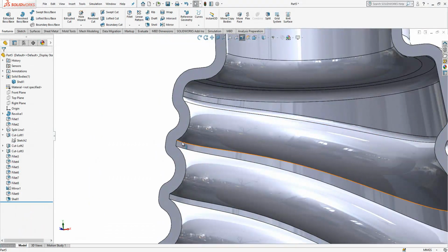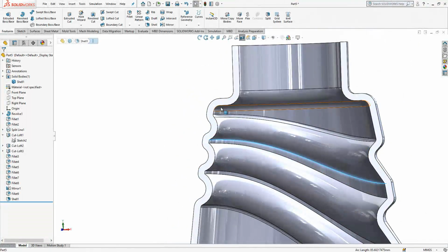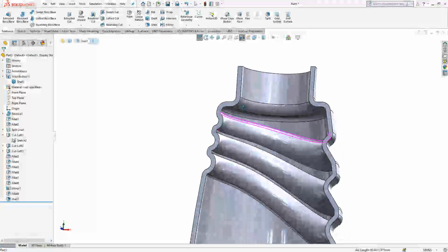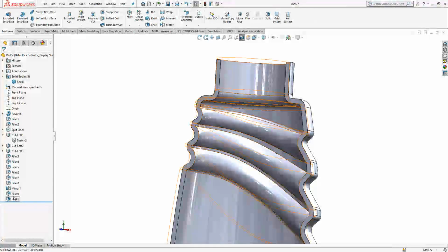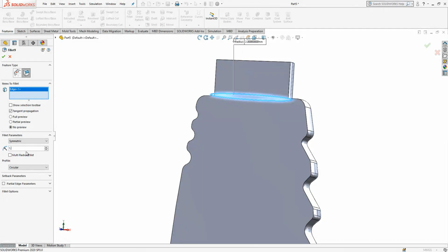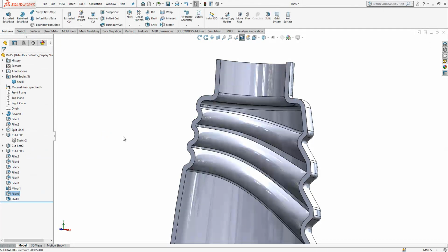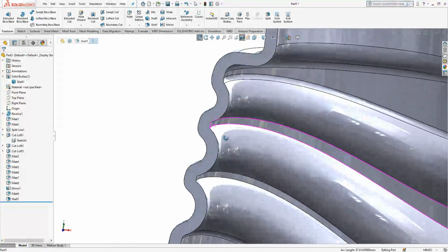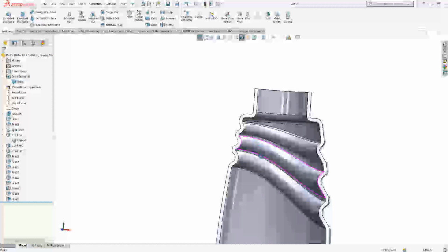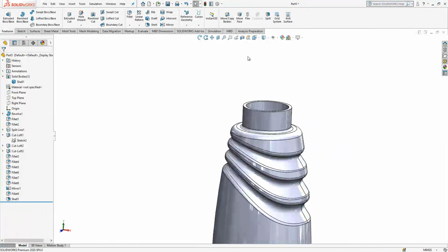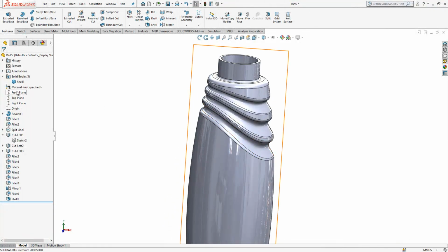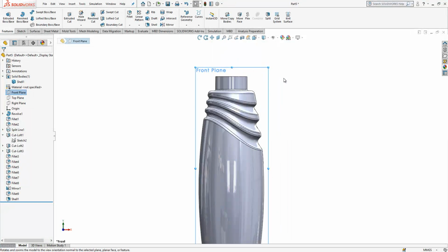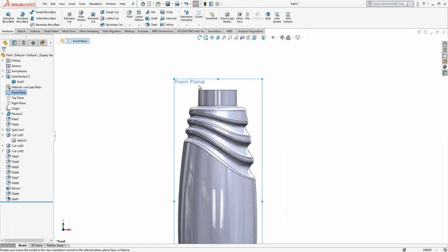You see here, these are sharp objects, and you want an equal distribution of thickness inside, because then you're going to have the equal distribution of heat, also heat dissipation, and that will affect the end result significantly. So you need to keep these things in mind. Know how thick you're going to make your object, and still you see here there is no radius, and based on that also define your radiuses. This is a tutorial. I don't mind to make it now radius 2 4 5 1, but in the real production these things going to matter a lot, so keep in mind.